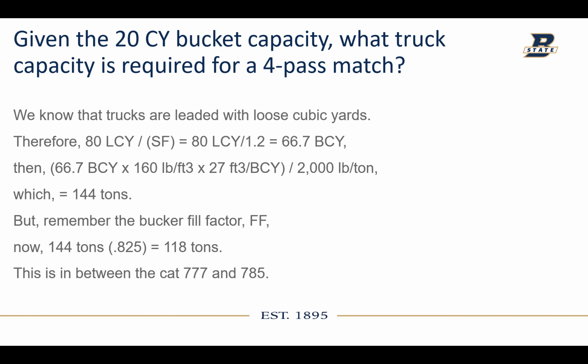So, given that we have a 20 cubic yard bucket capacity, what truck capacity is required for a 4-pass match? If you remember, last time I said that typically trucks are loaded within 3 to 5 passes. I've read that that's a little bit different than what I was taught, and it's now 3 to 6 passes.